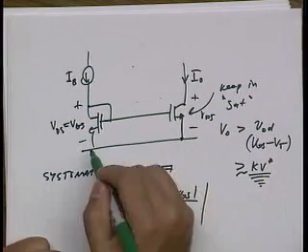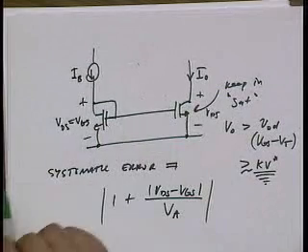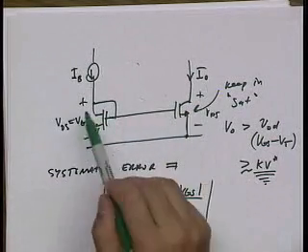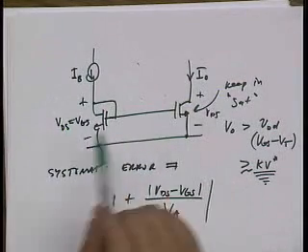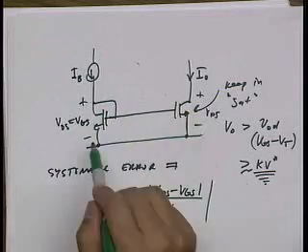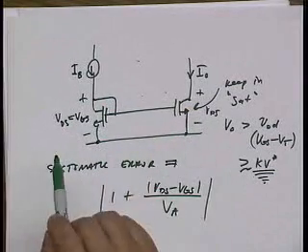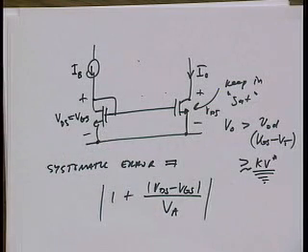That's pretty much it. Of course, if we don't lay out these devices correctly, there's going to be other kinds of systematic error. Definitely you want to lay out these devices close together with the same layout, right? Even though in theory only the W over L ratio is important, you better use the same L, right? And so that means use the same W for both transistors.